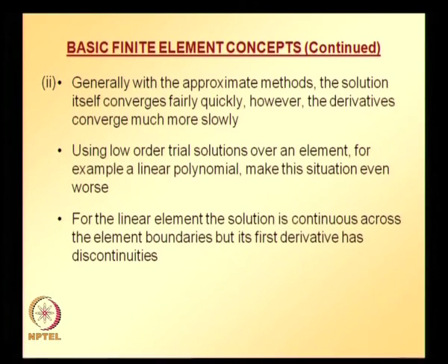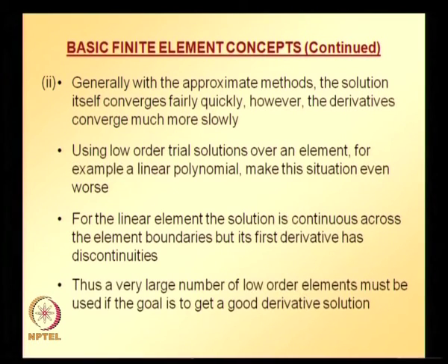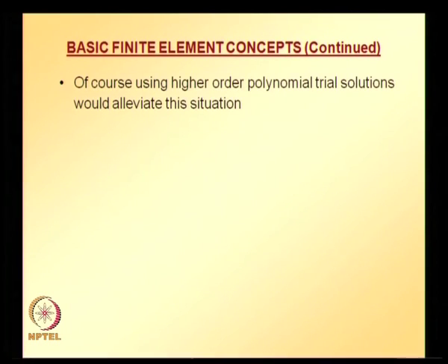For linear elements, the solution is continuous across element boundaries, but its first derivative has discontinuities. And if you want a good derivative approximation, you need to use a large number of lower order elements. Of course, you can also use a higher order polynomial trial solution to alleviate this problem.